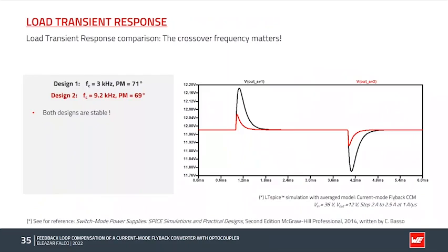And here we have the transient response for the two compensator design solutions. This was obtained with LT-Spice and also using an average PWM switch model, and that is the reason why we don't see any switching ripple noise on the waveforms.